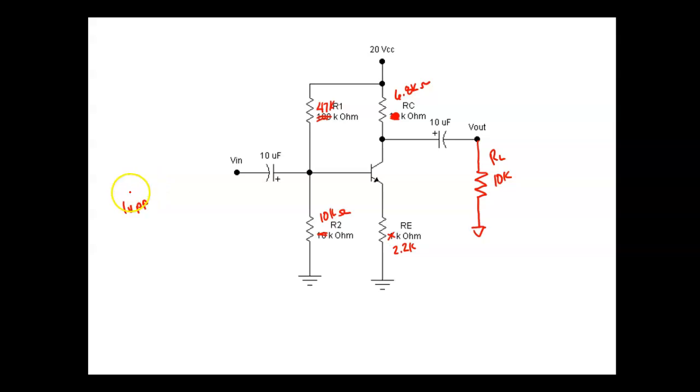and then they're bringing this out, so it's an AC source, and then they're bringing this out and going to a fixed voltage divider. So what we're going to do is bring an AC input in, but what they're shooting for right here is 10 millivolts peak. Somewhere in the procedures it says adjust it till we get 10 millivolts.